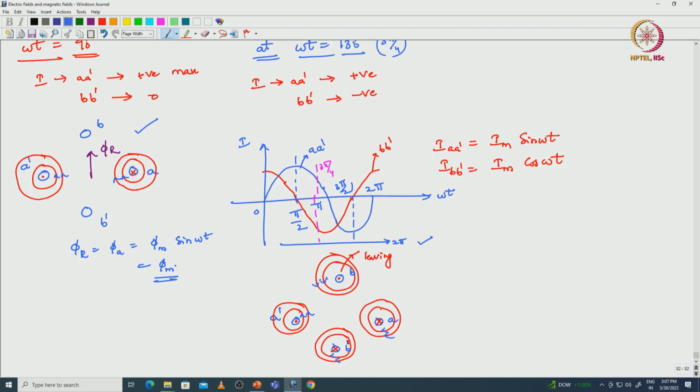So, here these two flux loops are in an additive manner. This is flux loop 1 and flux loop 2, the conductors which are carrying the same current, and those flux loops with respect to those conductors are in an additive manner. So, the resultant flux loop will form in this manner, and the direction is in this manner, phi r.